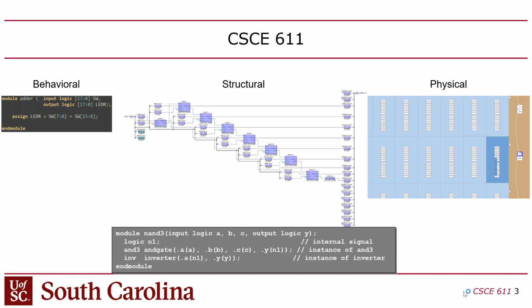So this structure actually comes from Quartus. This is the compiler we're going to use. So this structure was, I think I compiled it from there. I don't remember where that came from. Might have come from that code. But basically, you start out with code like that, and it compiles it into a schematic. Or you can write SystemVerilog that looks like this, that's structural SystemVerilog, in which case it still gets converted by the compiler, but then there's a one-to-one match between the two.